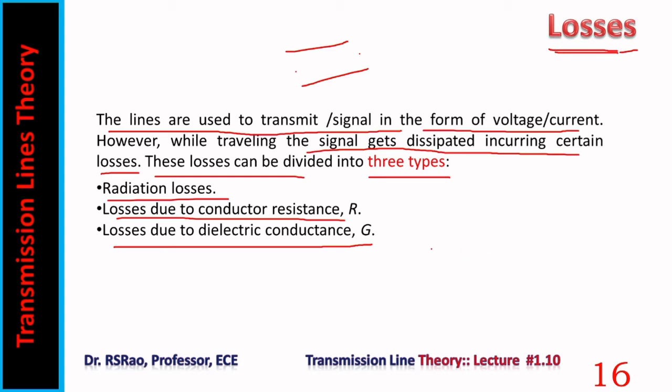So for understanding, we consider a small line. The signal is traveling. This is an electrical signal. Now, this is an open wire line. It is open, it is in space. So what happens is radiation occurs. The signal tends to escape into space. The nature of the signal is such that with increasing frequency, it has more tendency to escape. So signals of high frequencies tend to escape into space, never to return again. It amounts to losses. These losses are called radiation loss, because it is radiation escaping into space from the wire.